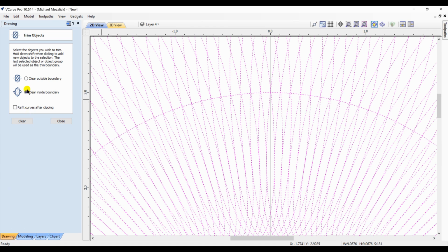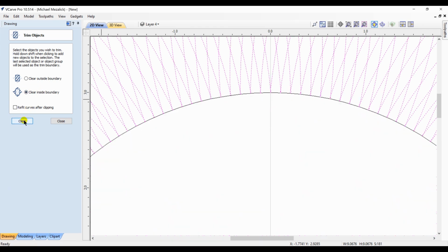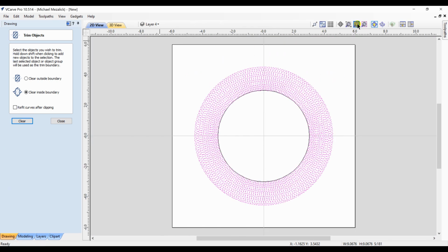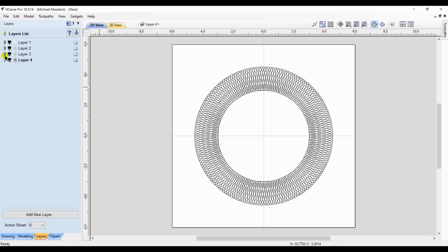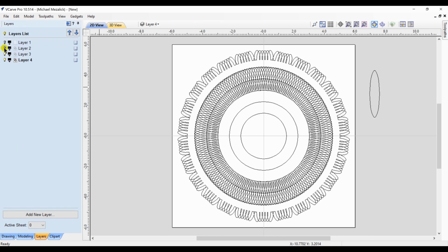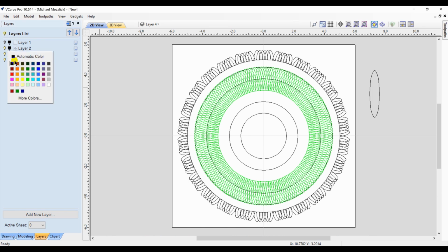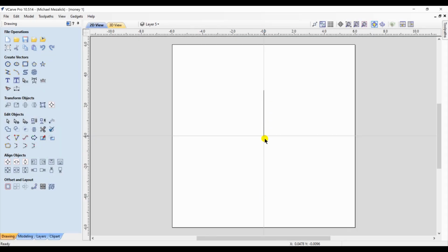I used this tool in the previous video of stacked text with 3D components. As we develop this, I changed the colors of the vectors so I can actually visibly see how things are turning out. For the center section, I draw a vertical line, a vertical vector, and again, I'm going to copy it around the center 26 times.